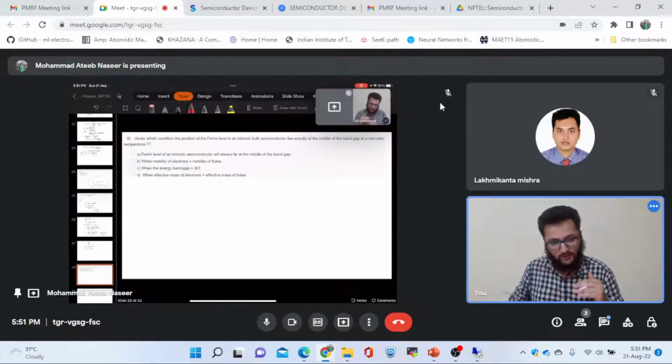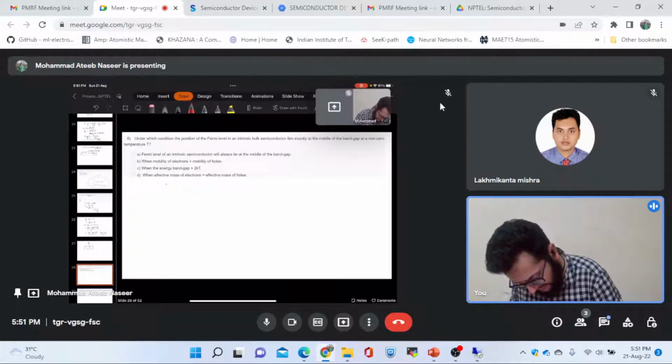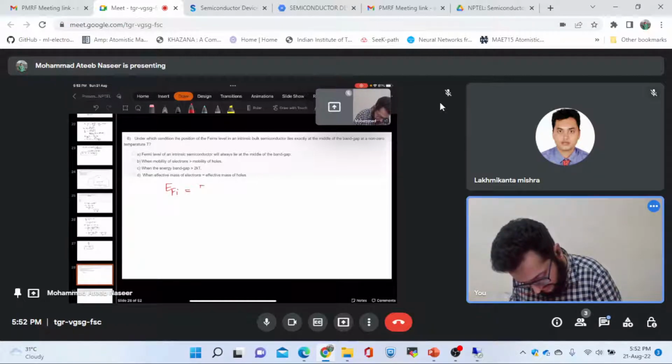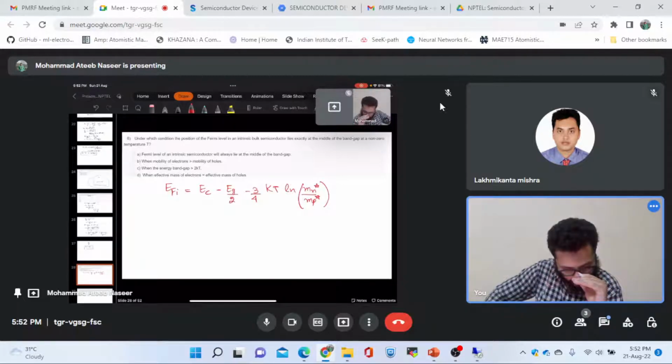We have been taught by the professor, and I will simply use that relation, that EFi, where EFi is the intrinsic Fermi level, will be Ec minus Eg by 2 minus 3 by 4 kT ln of Mn star by Mp star.